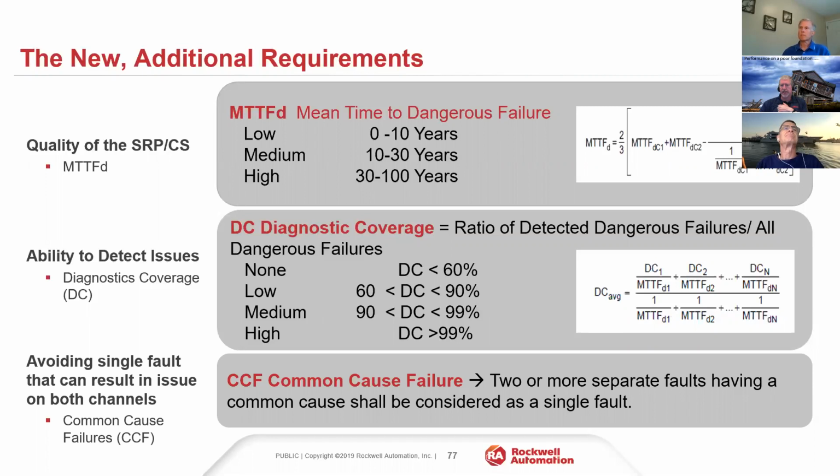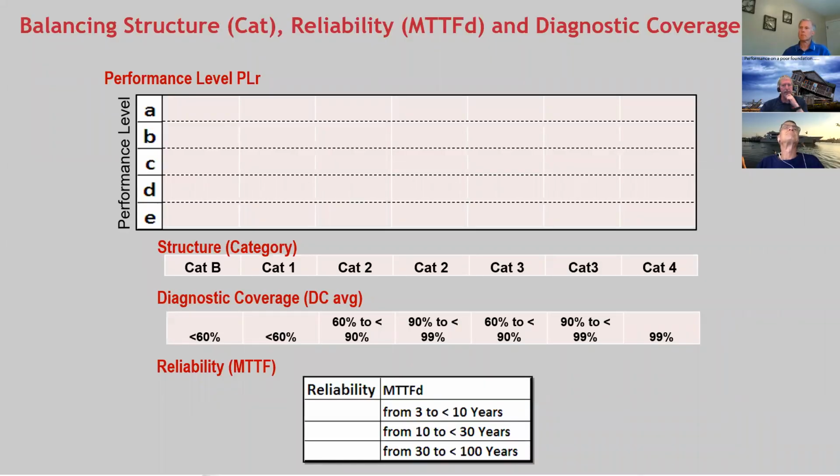So just to give you a sense of this, in the standard, there's a cute little chart, and I've changed it to be a little easier, I think, to understand. And we build it as we go, right? So let's tie this into how this may really work. We're following our safety life cycle. We've done our risk assessment. If you may recall, if you were on yesterday, when we do our risk assessment, depending on which standards we used, RIA TR 15.306, right, which was a technical reference to the robotic standard, the RIA 1506 standard.